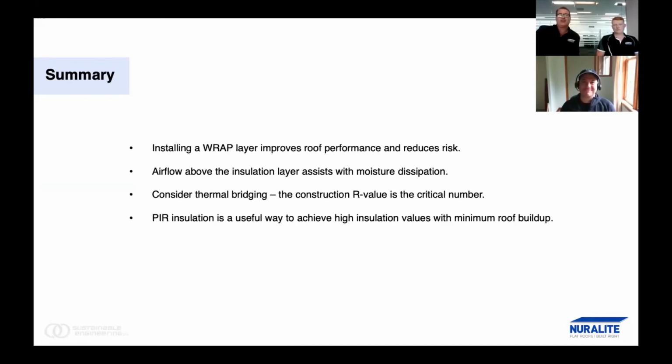I like this question. Can we use a good polythene as a vapor barrier instead of an aluminium foil? You could use a fully adhered vapor tight membrane there, which might include polythene as one of the layers. But I wouldn't just use builder's plastic. No. I have seen issues on site where joining the laps is very difficult.